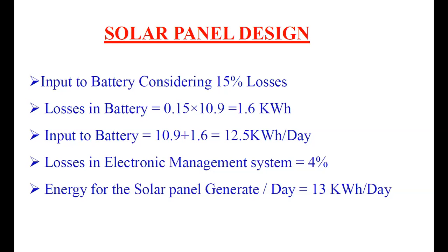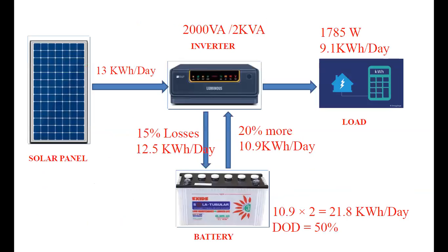Once again, we can go to the picture. The 10.9 kWh per day is the energy required at the input of the inverter. We are considering 15% losses in the battery bank.